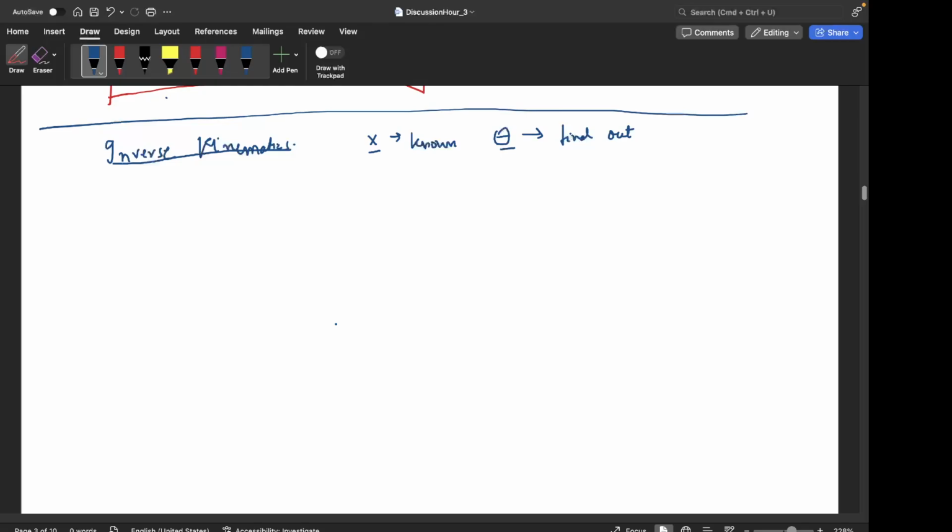Okay, so now this involves basically what we have in the forward kinematics case of a 2R manipulator, that is the end effector x is L1 C1 plus L2 C12 and the y is L1 S1 plus L2 S12.